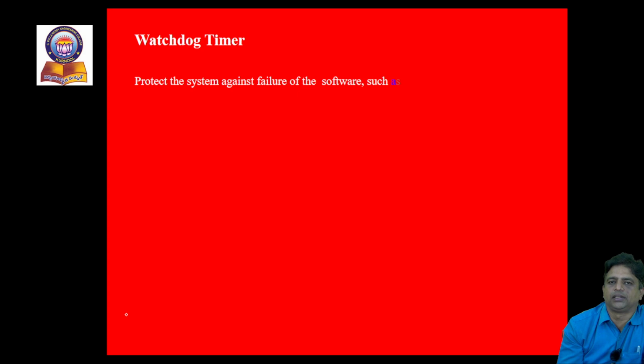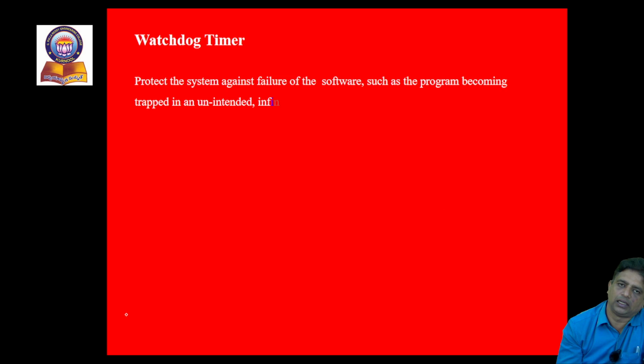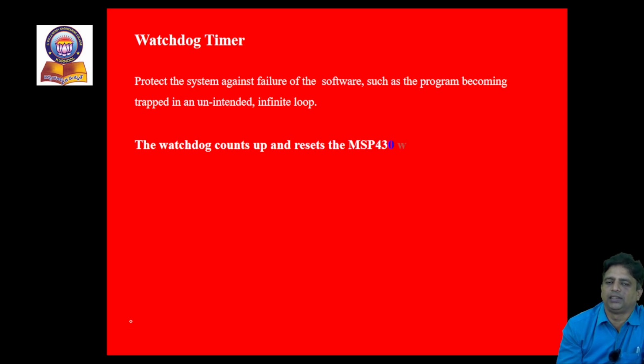What happens with respect to the watchdog timer is that whenever the processor or controller or ALU is stuck in some long executions or in non-resulting executions, or sometimes if the CPU has entered into a sleep mode and some operations are waiting to be executed, then the duty of this watchdog timer, as its name says, is to watch the CPU. It goes and activates the CPU, telling it: please come back to your active state.